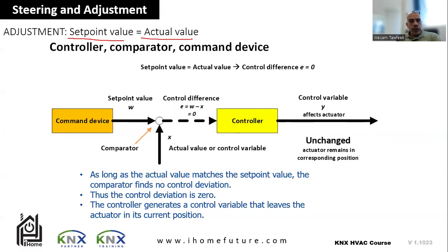And you will know this in the next chapter when we talk about the room temperature and how to control it. You will find that the thermostat in your room is always calculating the difference between the actual temperature that you have now and the set point temperature, or the temperature that you want to reach. And this difference is controlling the valve of the flow of water, affecting the heating or the cooling in the surrounding area around me, in my room as an example.